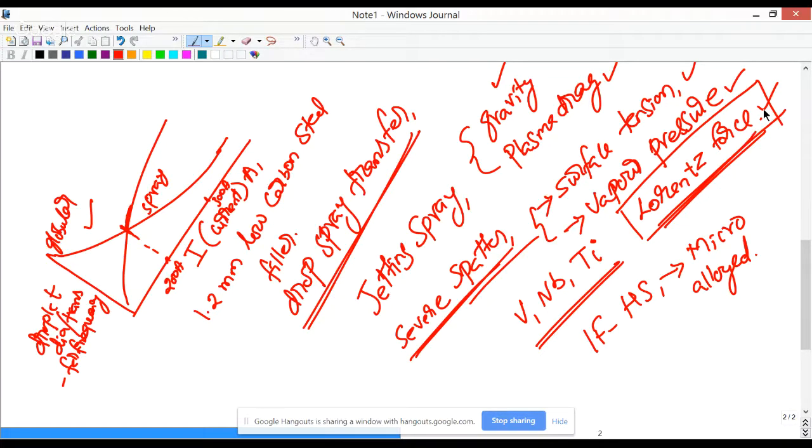And we also have a two-phase microstructure. One is really soft, one is hard. So obviously, the ductility of the ferrite matrix is much higher than the martensite. So when you're deforming it, the load is partitioned to the soft ferrite, leading to improved ductility.